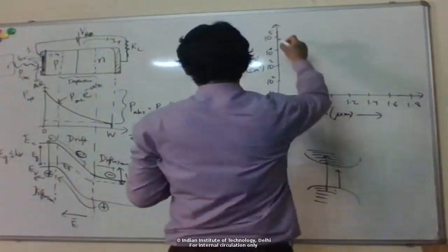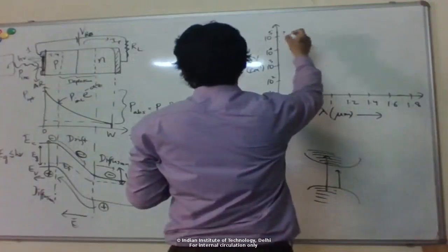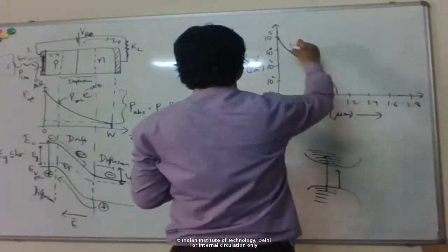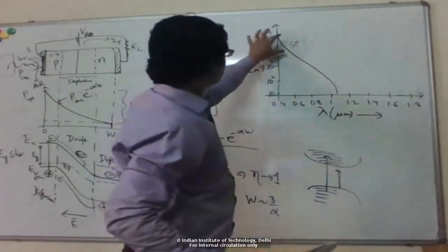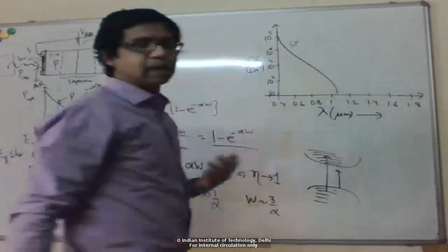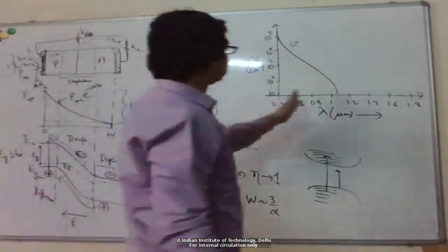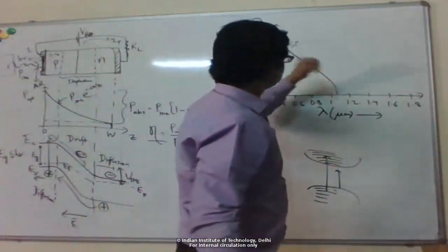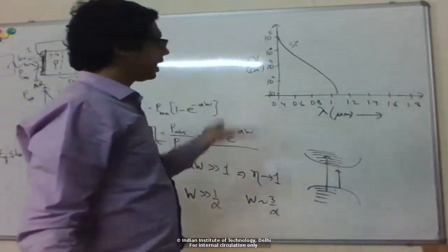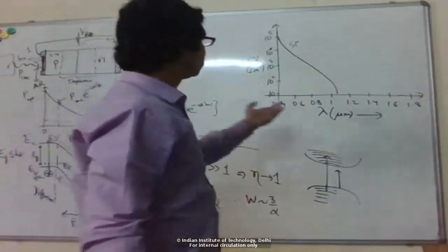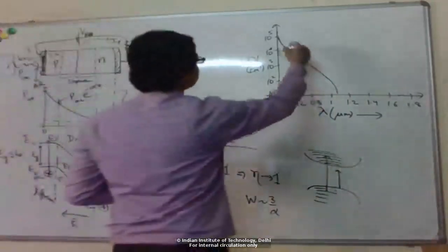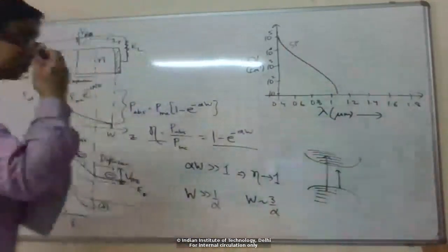You know that silicon is a popular photodetector material, and for visible wavelengths we use silicon all the time. Silicon has a very high absorption coefficient at visible wavelengths, but it falls off steeply because the band gap is 1.1 electron volts, which corresponds to about a micron of wavelength. Not only that, the band gap is indirect; the wavelength corresponding to the direct band gap is about 800 nanometers. So typically we use silicon for visible wavelengths below 800 nanometers.